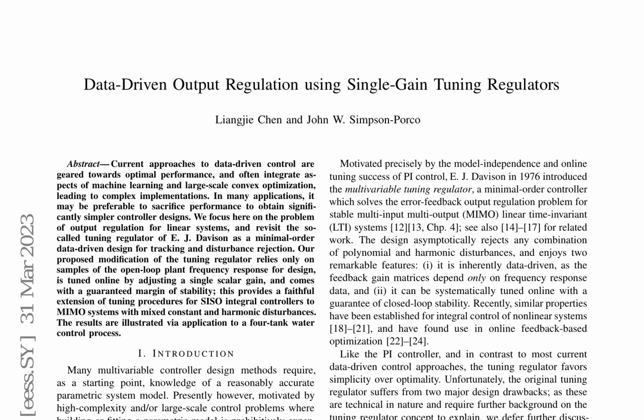The development of a single-gain tuning regulator, or SGTR, is presented for stable linear time invariant systems, with a focus on output regulation. Building upon the original tuning regulator concept introduced by E.J. Davison in 1976, this novel approach retains inherent data-driven properties and guarantees closed-loop stability when tuned online.